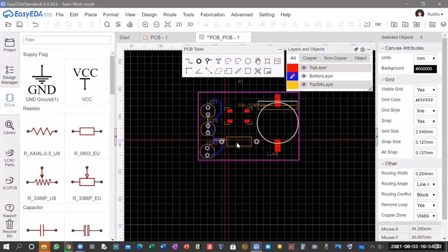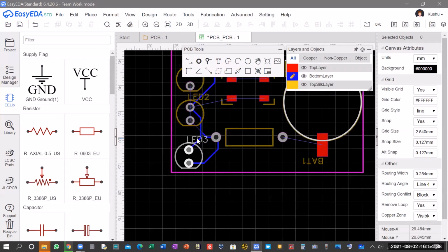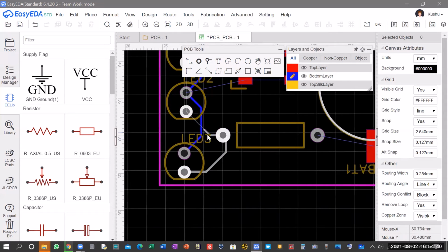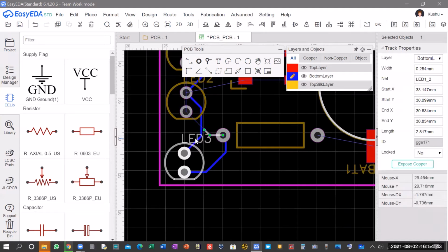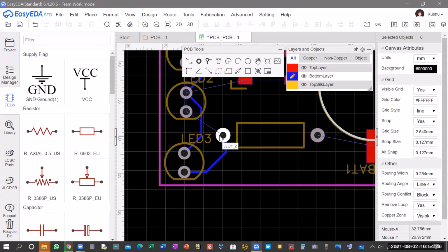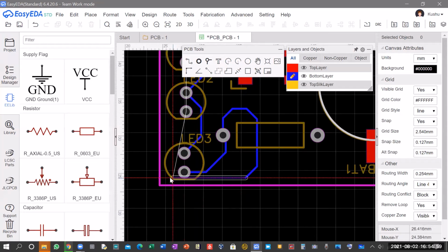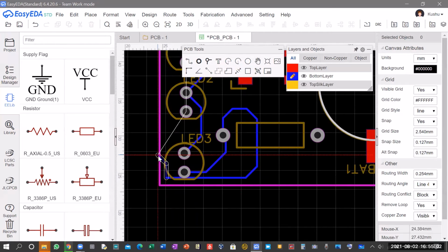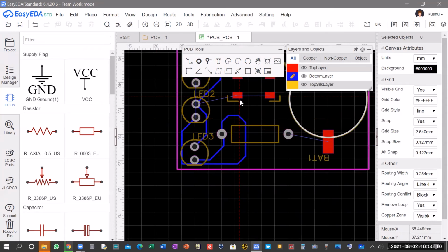Okay, so you cannot connect it to this point as there's already one wire going in here. So you have to be creative to get this wire past that side. You could do that like this. On certain component outlines, you can definitely take the wire through them. Like the resistor will be all metal film, nothing else, so it will not matter. Now I'm getting a sharp 90-degree turn here. That's not a problem if you get it once or twice, but as a rule of thumb, avoid them.